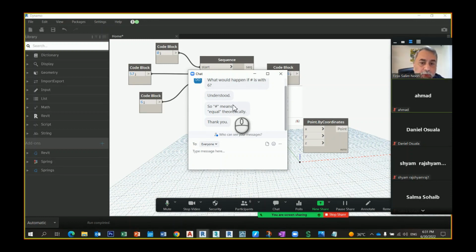If you put it with the number, then the number is not an increment by itself. It's going to be a jump of, or a division of, 6. So if the distance from my point to your point is 1 meter, pound 6 means we have to jump 6 times to reach you, and Dynamo will know the value of each jump. Now Dynamo will divide the distance to create 6 equal jumps to you.